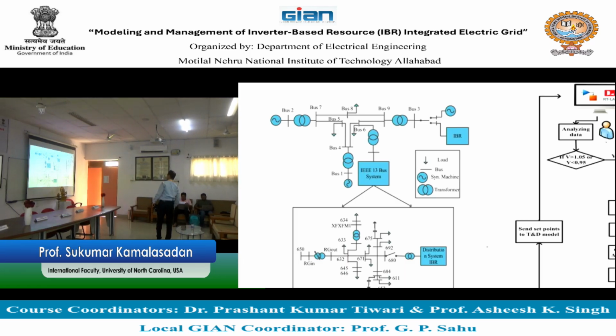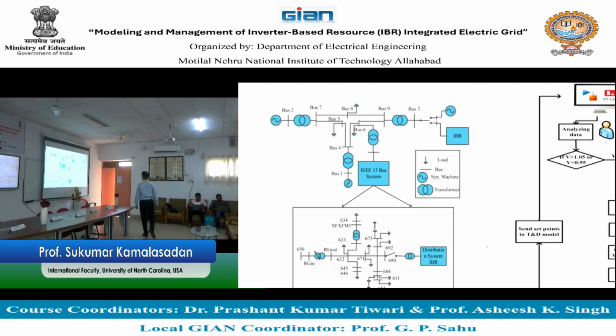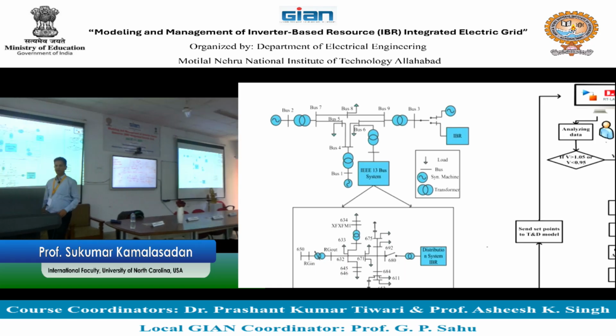Have you heard of this distribution network? This is another distribution network model which is very extensively used. This is the 13 bus distribution model which has an unbalanced 3-phase, 2-phase, single phase model. And then you have DERs connected at different points in the distribution network.